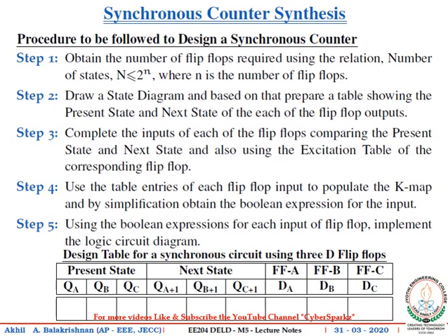Next is synchronous counter synthesis. A synchronous counter is a counter circuit in which all the flip-flops are provided with the clock signal simultaneously. Since the clock signals are obtained simultaneously, the flip-flop output depends upon the synchronous inputs of the flip-flop. So in order to get the required output of the flip-flop, we need to provide the proper set of input signals. To decide the proper input for the required output of a flip-flop, some logic circuitry must be used along with the flip-flops.